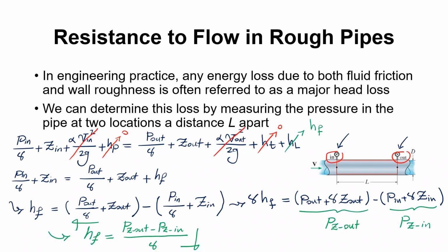And that alternative method is an equation called Darcy-Weisbach method. So it is spelled like this: Darcy-Weisbach method or equation. This Darcy-Weisbach equation allows you to calculate HF for laminar and for turbulent flow using velocity of the flow that can be measured, length of the pipe, and diameter of the pipe. So much easier to measure, right? This equation can be developed for laminar flow and turbulent flow. So it is very versatile, and you can use it for any type of flow that you have.